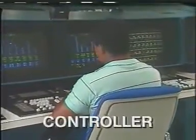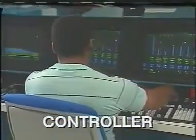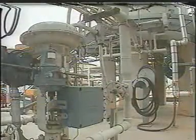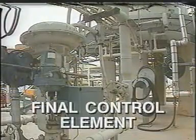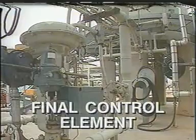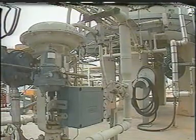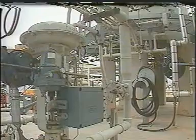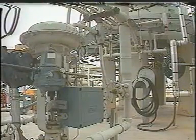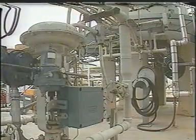And we need a controller like one of these to receive the measurement signals and compare them with a desired value. A valve like this one is the final control element in the loop. The valve regulates the flow of fuel gas to the furnace. If oil temperature rises, the valve will get a signal to decrease the gas supply. If oil temperature drops, the valve will increase the amount of gas to the furnace.